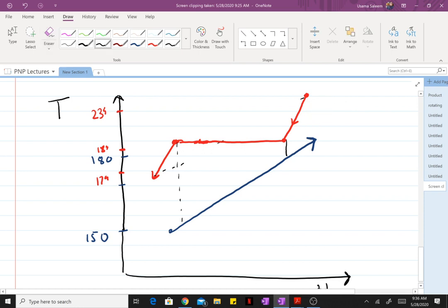So I'm going to call this section 1, the subcooled region. I'm going to have section 2, the saturated region, and I'm going to have section 3, the superheated region. Now there's a problem. We know all of the intermediate temperatures for our heating utility. We know it enters at 234, it becomes saturated at 184, and it exits at 174. But we don't know the intermediate temperatures of our process stream. Like, what is the temperature here? What is the temperature here?